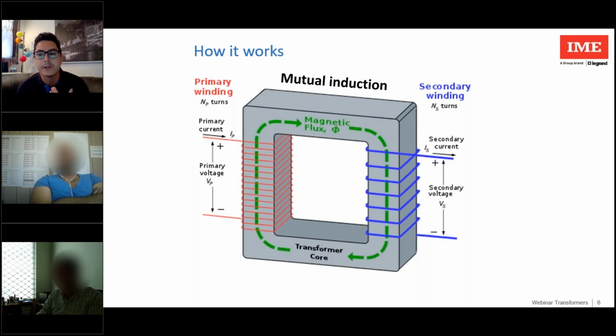The efficiency of the transformer is very high and the losses are very low: in the iron, due to the hysteresis effect and eddy currents, and in the copper, due to the Joule effect. If an electrical load is connected to the secondary winding, an electric current flows, and the energy is transferred through the transformer from the primary circuit to the load.